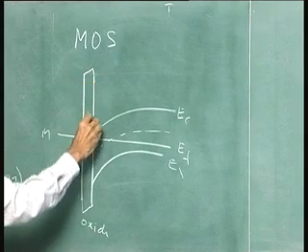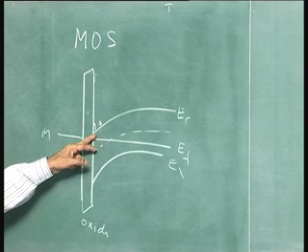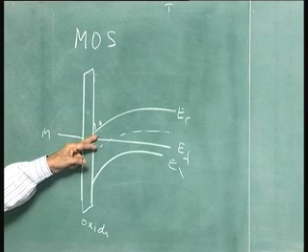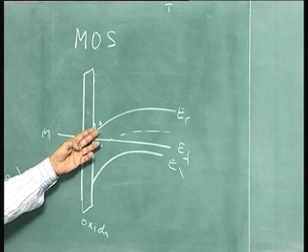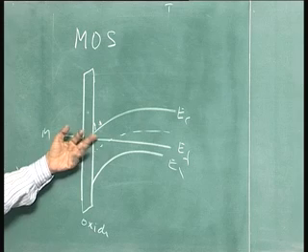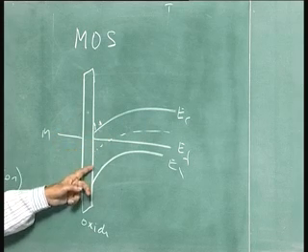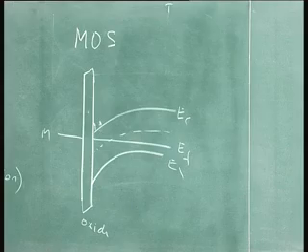Conduction band of oxide, and this is the region where the electrons are. There is a notch, exactly similar to the case of HEMT. The electron concentration may not be as high as you can get there, but you can go into inversion region here, and they are locked up there because of this barrier. So, the same thing is occurring here. In fact, you can see one-to-one correspondence between the MOSFET and the HEMT.